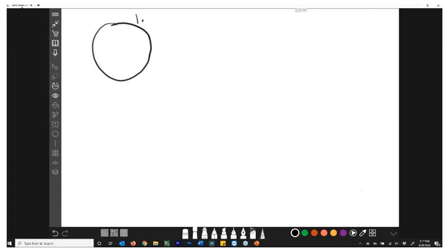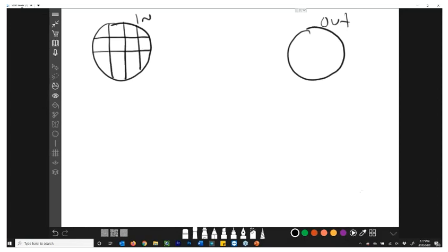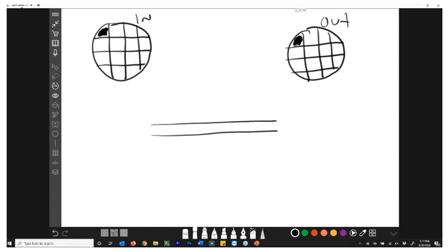So let me draw you here an example of what we're looking at. On the DOC, if I drew the inlet and I drew the outlet, okay, what you're going to notice, if you were to look at this, and of course I've got a much larger blown up version of this, is a bunch of little tiny cells if you look at the inlet or the outlet. And all these little cells, it's kind of like a honeycomb substrate. So if my exhaust gas goes into this chamber on the inlet, my exhaust gas will exit that same chamber on the outlet, okay? So the same chamber the exhaust goes in is the same chamber the exhaust goes out, which means our DOC is a pass-through device.